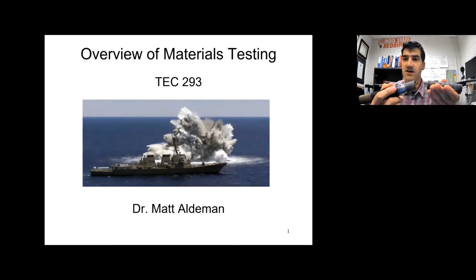In fact, like I said, there are about 50 of these going around the perimeter of the blade, so we can actually still operate the wind turbine even if we're missing one of these. If we're missing more than one of these, then you're not allowed to operate the wind turbine anymore, just for safety measures. But when one of these breaks, it's not supposed to, and so we had to send this back for some testing.